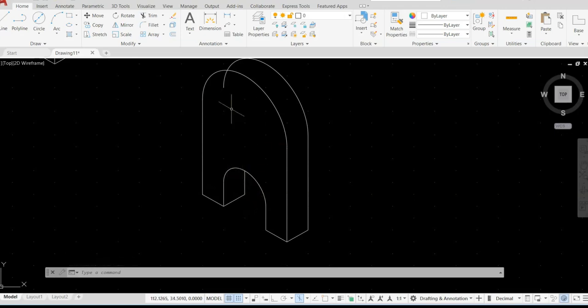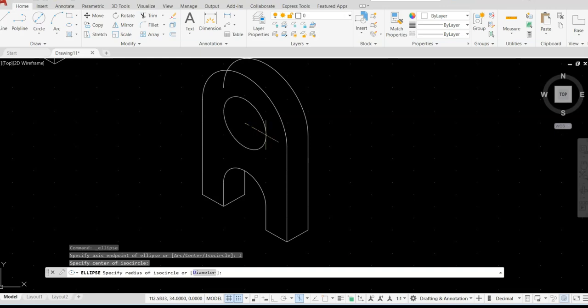Now let's have the circle over there the same way, axis end, and here's the circle. The center of the circle is that point. Click on it. Now click on the other diameter. This one we need also to copy because there is a little part coming from that. So let's make copy circle, enter, and this point to this point, enter. Now we need to do trimming, TR, enter. Cutting edges is this circle, enter, then you trim the part.